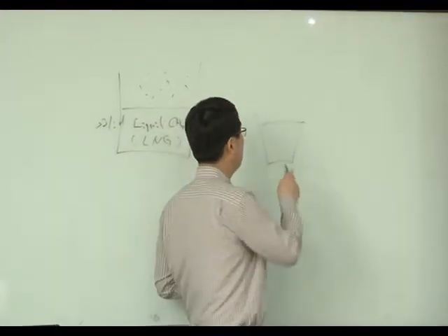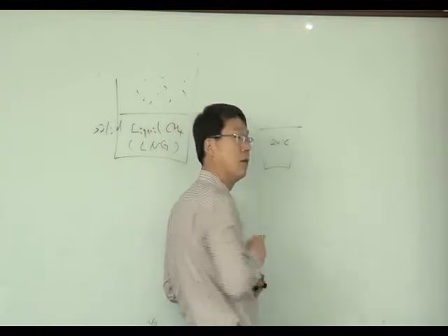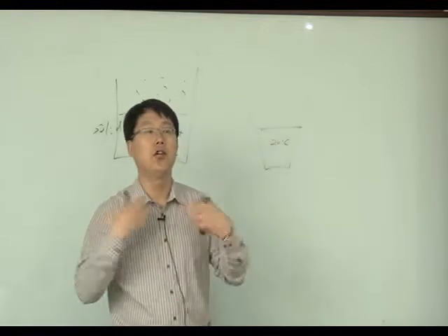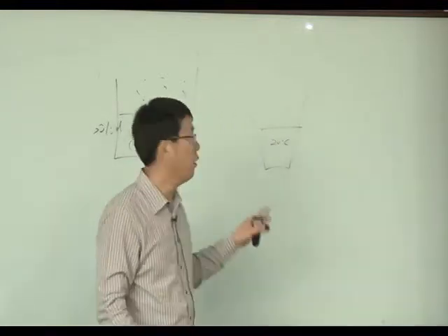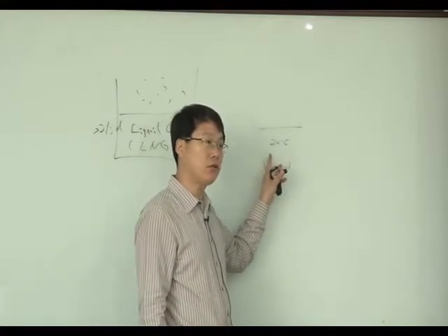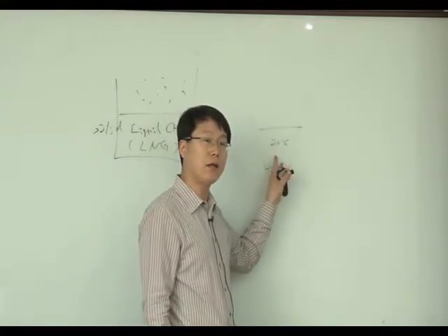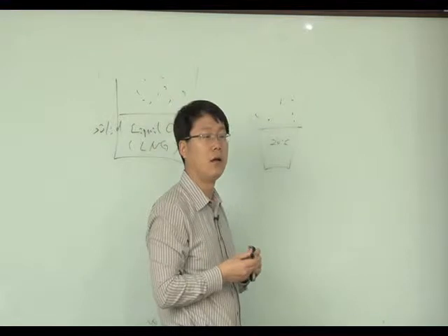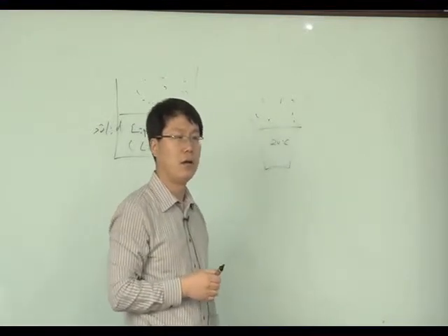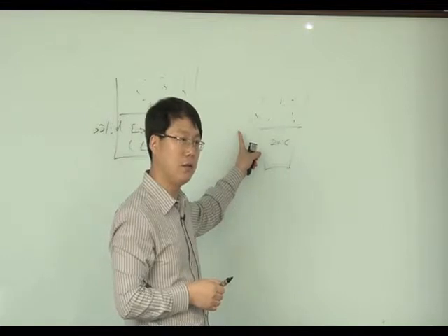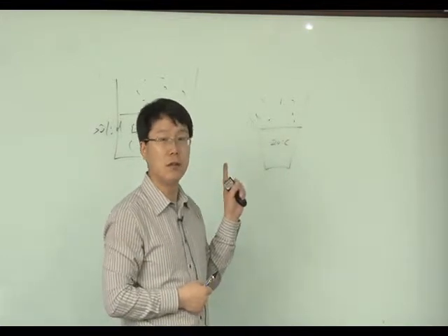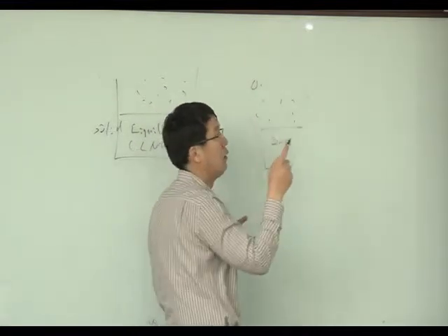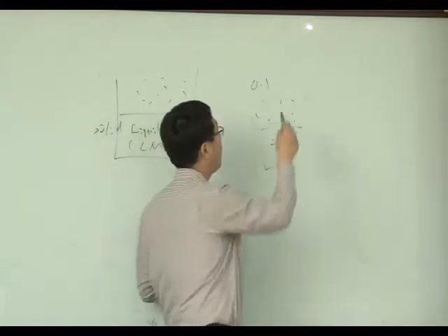The water temperature is, for example, 20 degrees Celsius, then this water will generate vapor, whose pressure is governed by the temperature of this liquid. So how much is it? At 20 degrees Celsius, it's maybe around 0.1 bar.